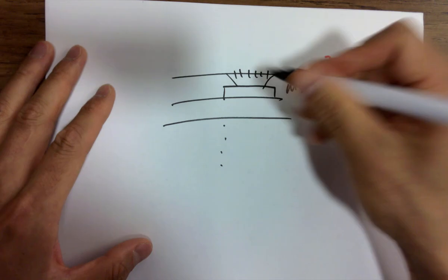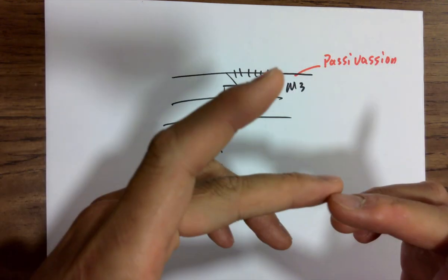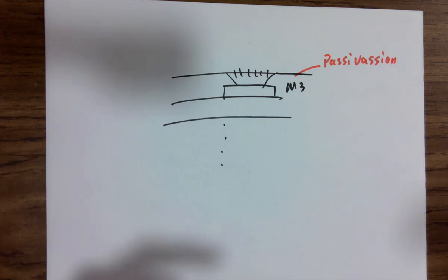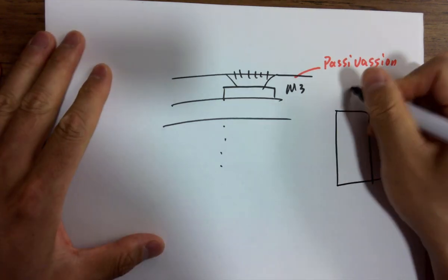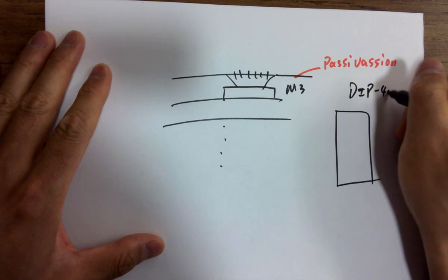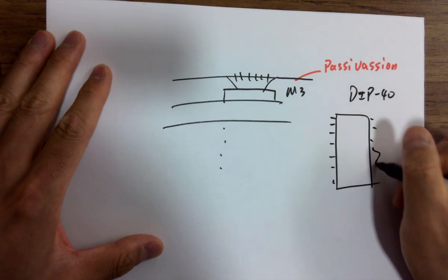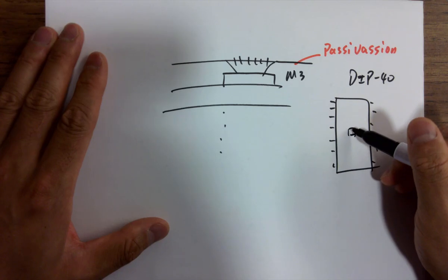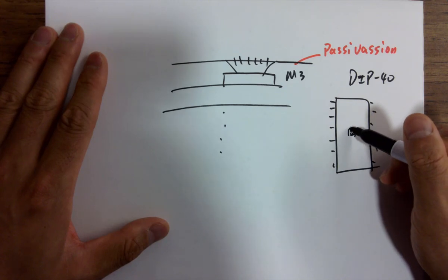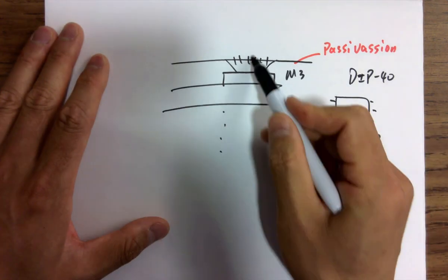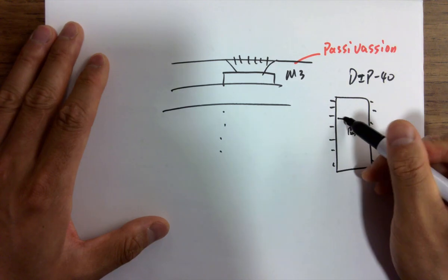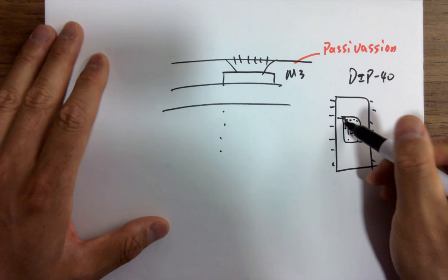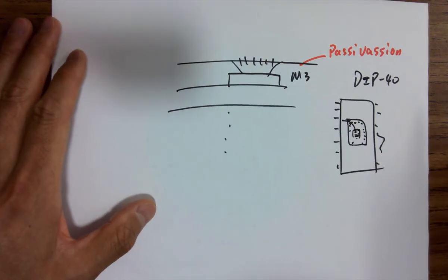And then you place this one in the package, like I showed you all the chips, right? Including all the Arduino chips, the same thing, it's a different package. So usually what we have is the DIP 40. Has 20 pins on each side, so it's total 40 pins. The very fundamental prototyping packages, and you can place your die in here, and these are all the pads around the chip, and every pad has an opening. Metal 3 has an opening on the top. Then you do these connections, right? So they have another package here, do the connection to the pads. That's how you do it with the wire bonder.